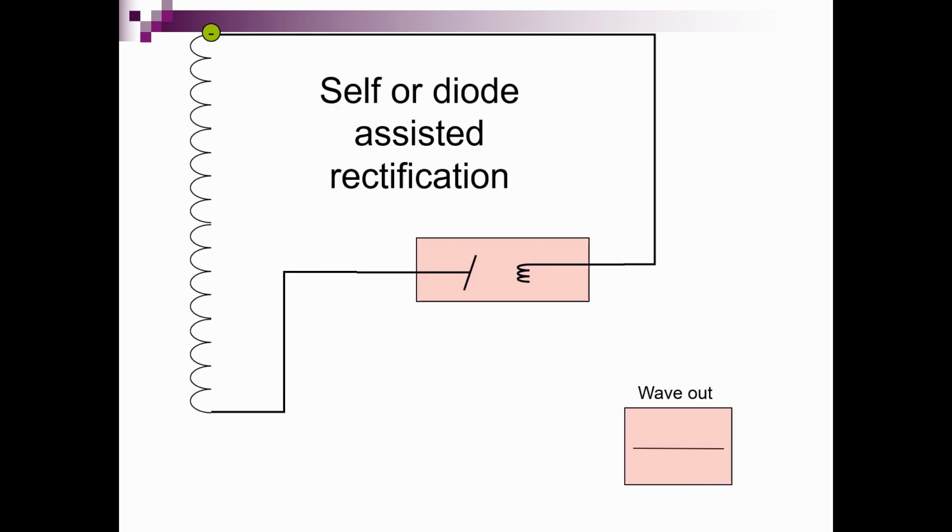In the early days of radiography, the X-ray tube could act as a diode and provide rectification for the circuit. A problem arose if the anode got too hot or if the kV was set too high. Reverse conduction would occur, damaging the tube.